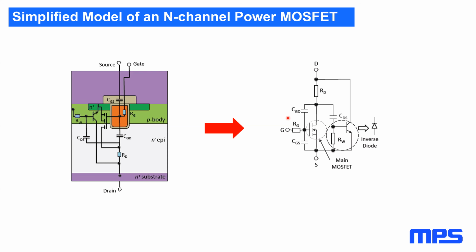Once the transition is complete, and some gate driver ICs will actually look at the drain terminal, so it can tell when it's nearly down to 0 volts for the low side. And then it'll put a hard clamp between gate and source to keep it turned off.